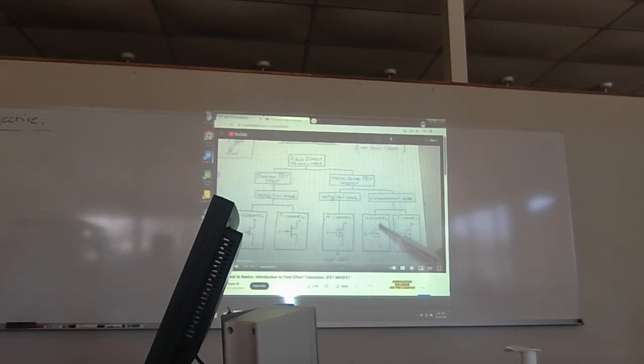Let's redefine depletion. We started out with the channel at max current, IDSS, when VGS was 0. Does that agree? Enhancement mode essentially does not conduct current when there is no gate to source bias. So what happened now? It's an open circuit. It's the opposite. You with me so far?